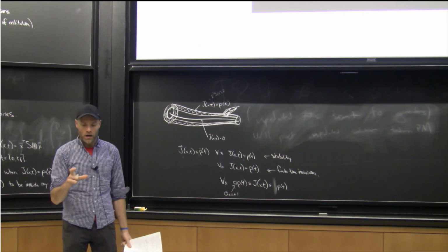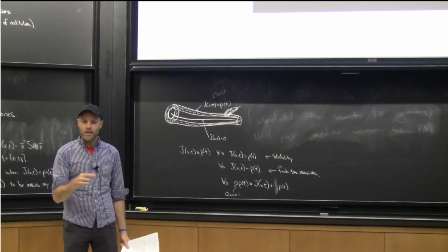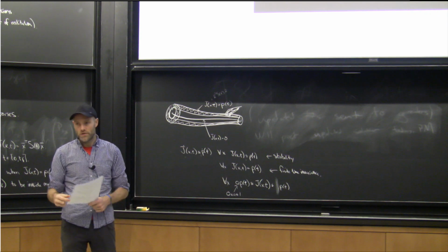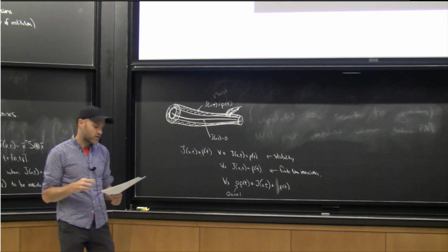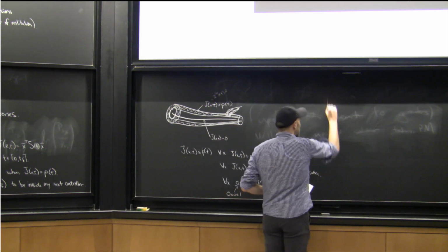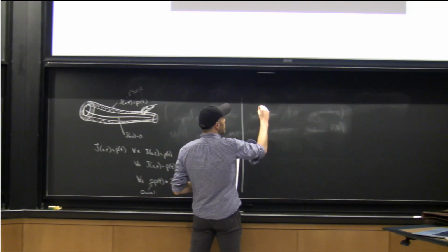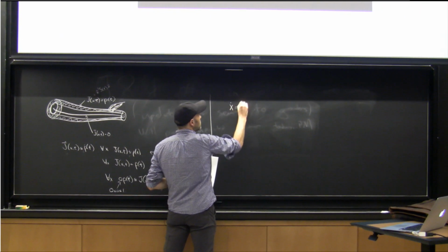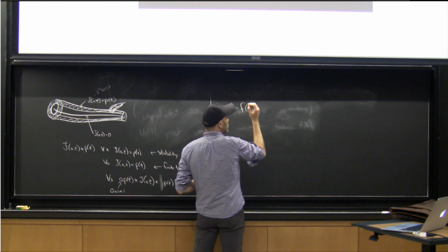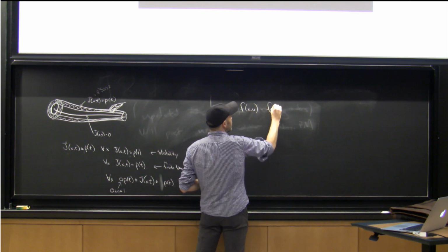And you can also, in the sums of squares iteration, search for better controllers at the same time. Okay, so the way that works is you parameterize. I can do the very cartoon version here first. So if I say x dot is f of x u, right, this was a polynomial, let's say, but let's say it's even control affine.